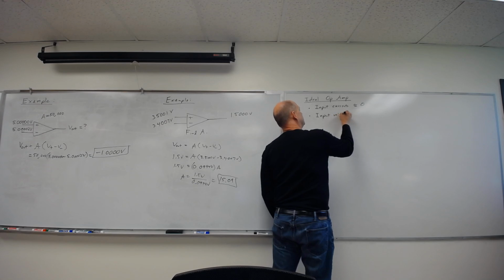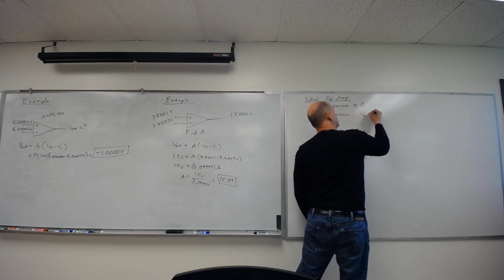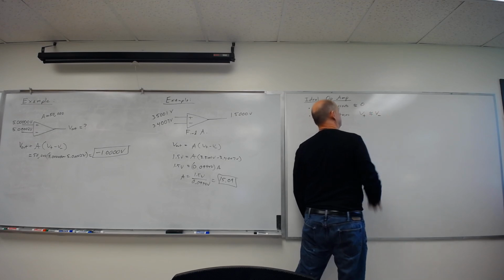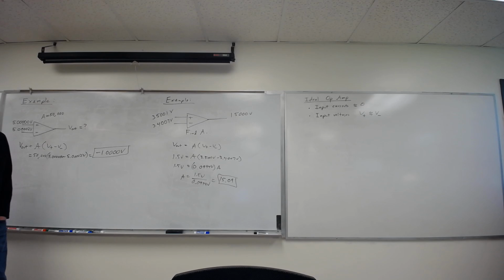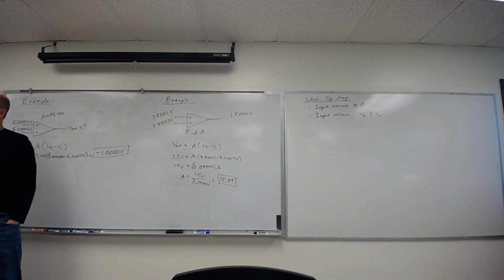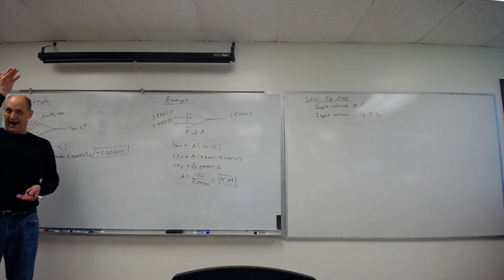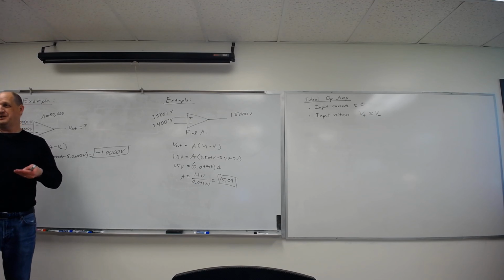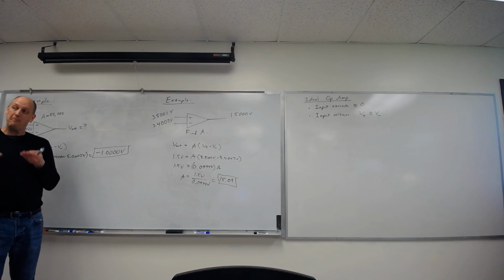Input voltages. The inverting is going to be approximately equal to the non-inverting. What we just saw in the last example, I guess I should explain a little more for we erased it because I was busy saying, hey, maximum 15 volt, is if I have one tied to 0 and the other is about anything, we're just going to max out the maximum number, positive or negative. So that means for there to be any interesting input, this thing's really designed so the two inputs are about the same, and we're only looking at that minute little difference.